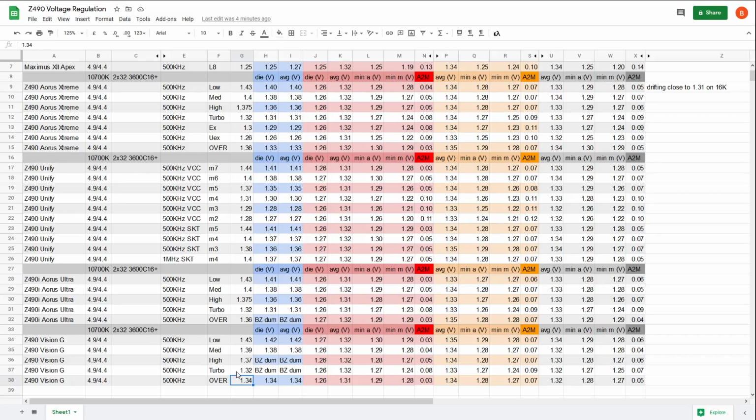I think Gigabyte might be tuning override mode with various BIOS updates, and then some boards might just have a slightly different implementation of override mode compared to other boards. This is a 30 millivolt difference in average voltage, and that's still 30, so it doesn't seem to be any more aggressive. And 0.307 versus 0.305, which is the same as the 0.307 we saw in the ITX.